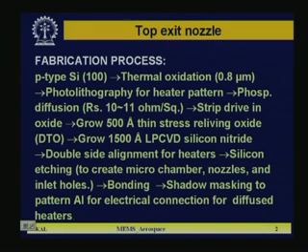The heater can be made using diffused resistance through silicon, and you can have this structure like a meander line. So, just like a coil, here instead of a coil you are using a resistance, which is a diffused resistance into the silicon. If you apply power to that, the embedded resistance in the silicon will be heated, and since silicon is a conducting material, the heat will be transmitted into the propellant. So, phosphorus diffusion is made